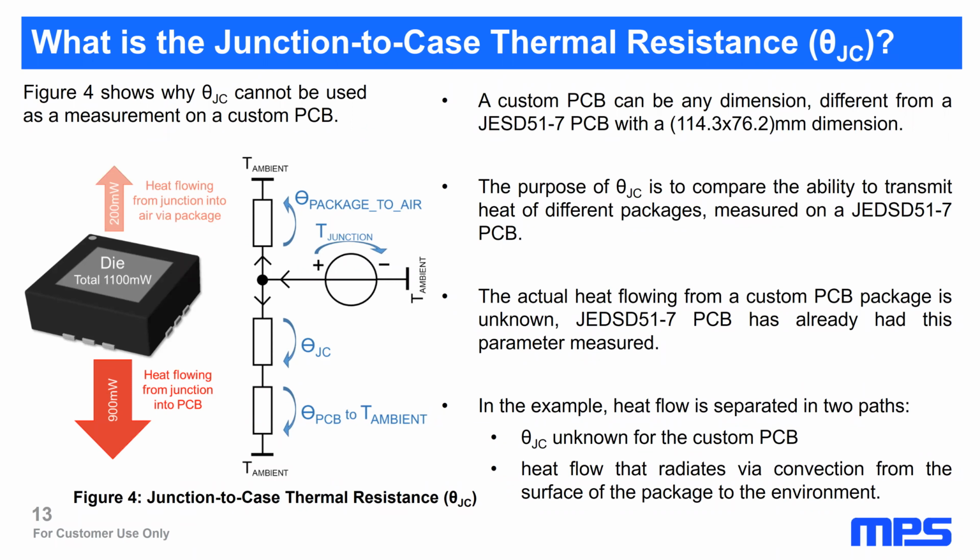Every custom PCB is always different from the JESD51 PCB. The dimension is different, the copper is different, the number of layers is often different. The purpose of theta junction case is to compare the heat flow of different packages if they are measured on the JESD51 PCB. The actual heat flowing from a custom PCB is always unknown. Only a standard PCB like the JESD51 has had this parameter measured.